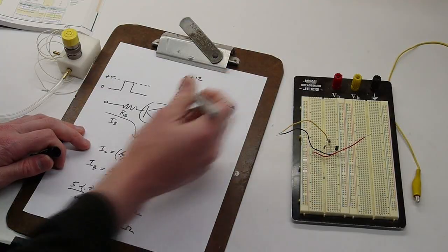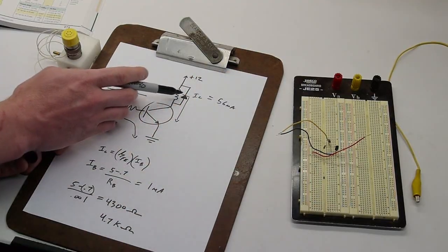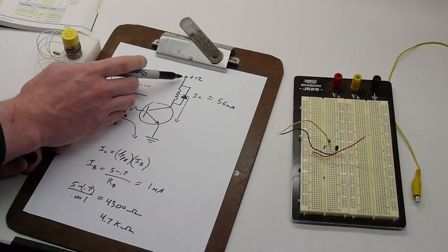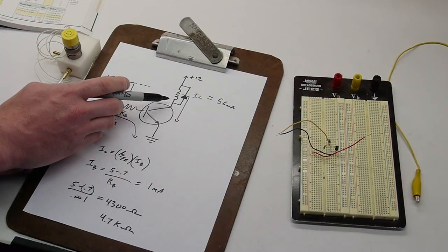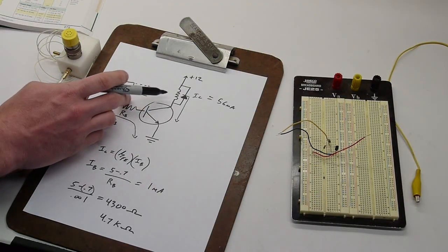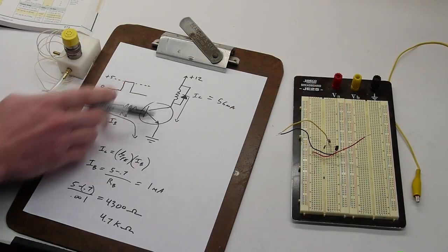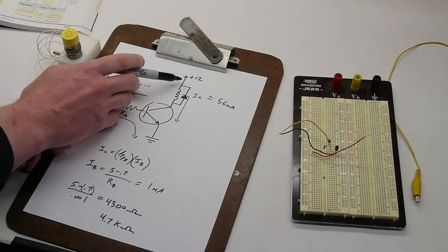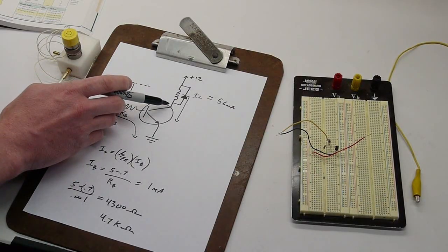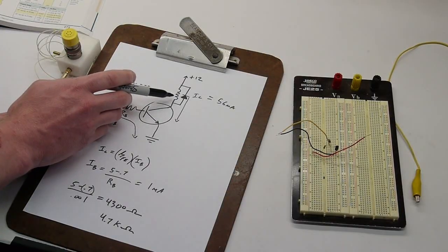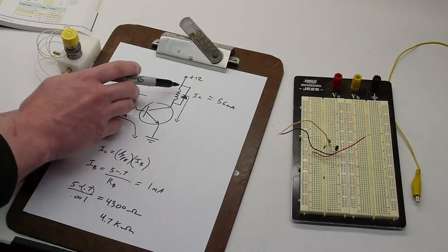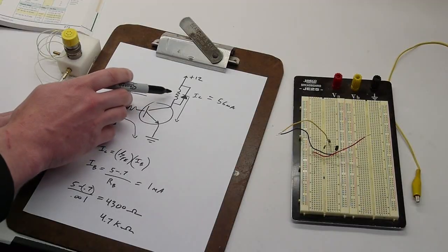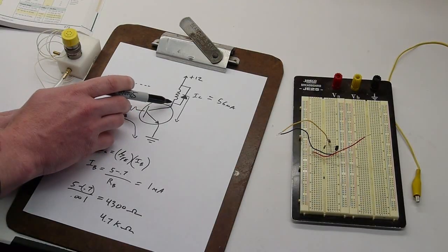So you might be thinking, well, that's stupid, but I mean, the diode is pointing into our voltage source. How could this ever get higher than plus 12? And the answer is that when the transistor turns off, all of that current that was flowing through this coil has created a magnetic field in here. And when the transistor turns off, that magnetic field collapses and the voltage is going to rise at this point. It could be quite significant.